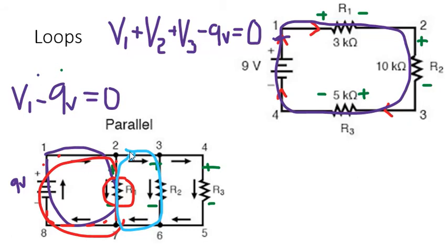Well, if I draw this loop, plus the voltage of 3, and then I keep going around. I know we covered it up, but we hit the minus side of resistor 1. So minus the voltage of 1. I'm back to my starting point. That equals 0. Well, that tells us, sorry, let me make one quick change. Plus the voltage of resistor 2. So that's resistor 2. Minus the voltage of resistor 1, because that is resistor 1, equals 0. Well, that's just telling us the voltage of resistor 2 and the voltage of resistor 1 have to be the same.